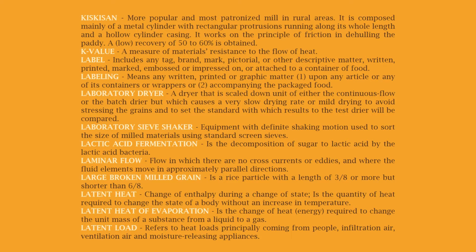Laboratory dryer. A dryer that is a scaled down unit of either the continuous flow or the batch dryer, but which causes a very slow drying rate or mild drying to avoid stressing the grains and to set the standard with which results of the test dryer will be compared. Laboratory sieve shaker. Equipment with definite shaking motion used to sort the size of milled materials using standard screen sieves.